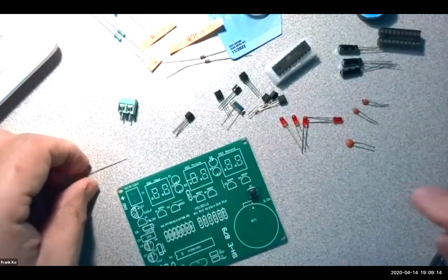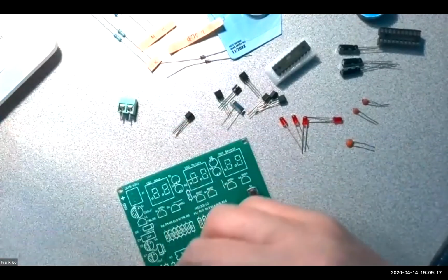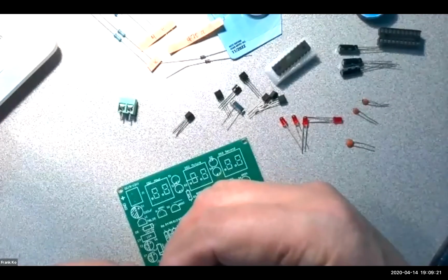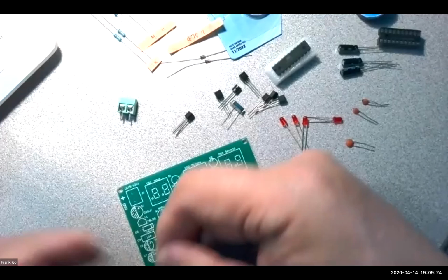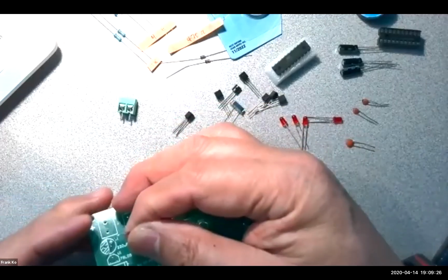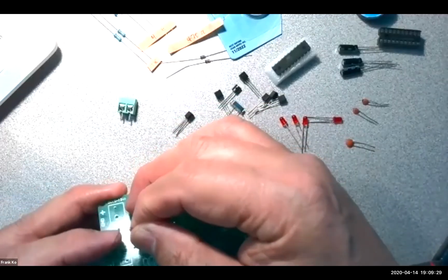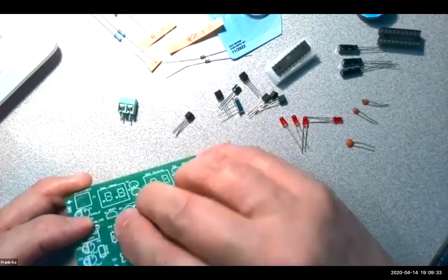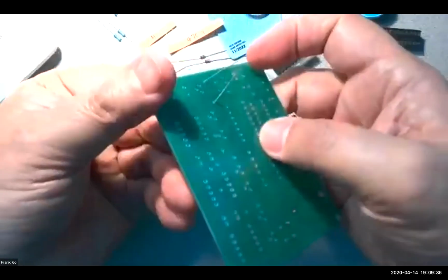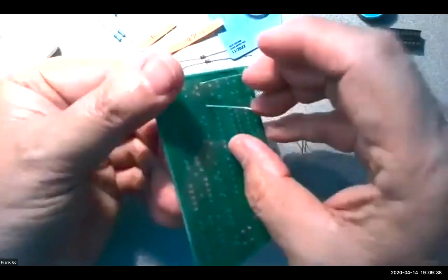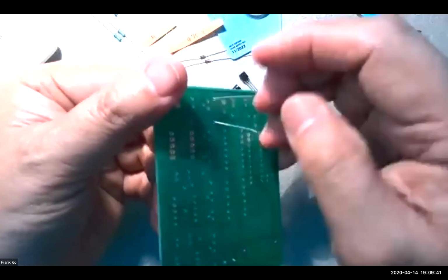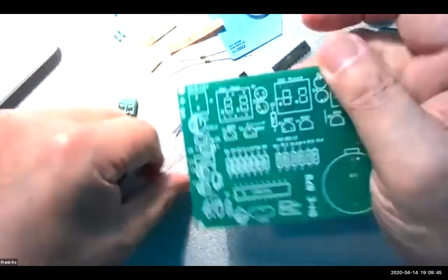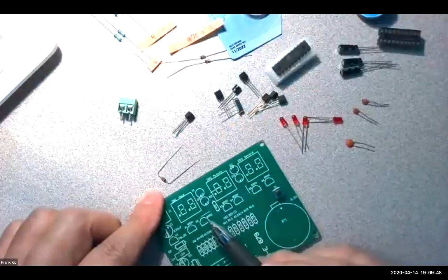So when you put your diode on the board, go ahead and get one of these diodes on the board here for you. Let's bend this guy here and bend this guy here. Much nicer if I did it with pliers, but I'll just do this real quick. This diode will go here, and this diode will go here. You see how much wire we have left over? You'll be using these wires after you solder and snip them in place. You have plenty of these wires left over between all the resistors and the diodes that you're going to be putting onto the board for the jumper wires here and here.